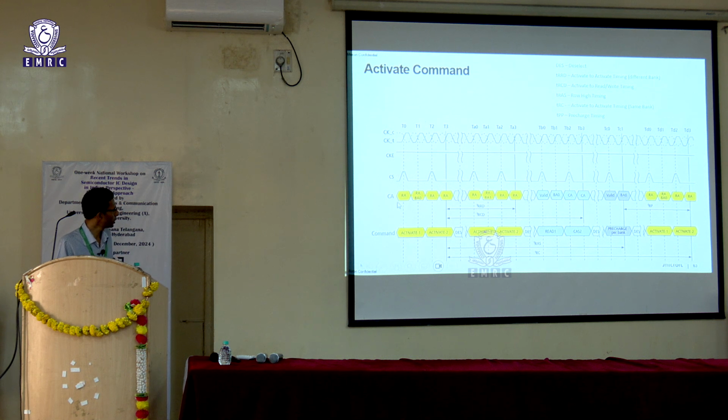So, you are transferring it over 4 different cycles here, and this is row opening for one particular bank, and similarly after some time you can do a row opening for a different bank. And so, the row to row operation is tRRD, and there are multiple other such timing parameters that you would be interested in in the DRAM world.